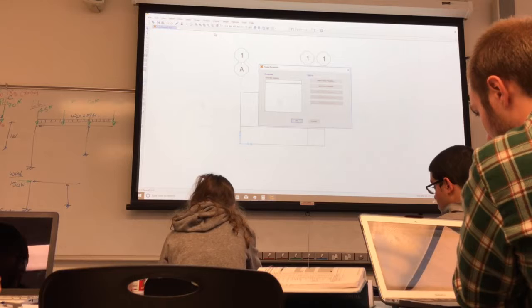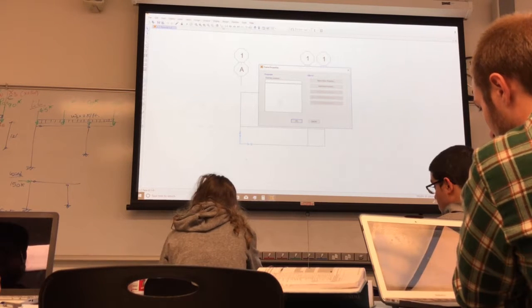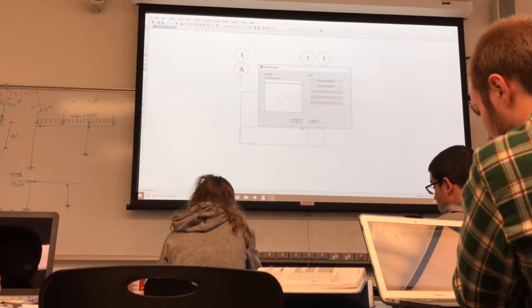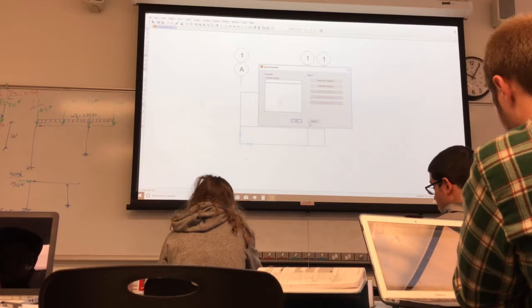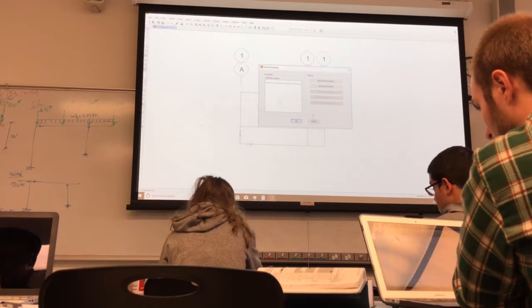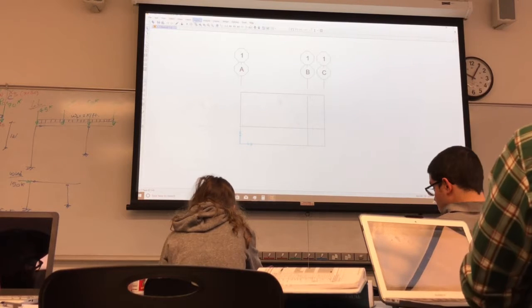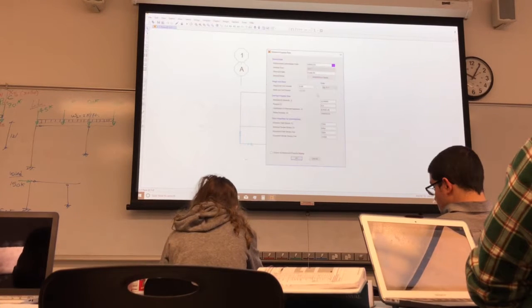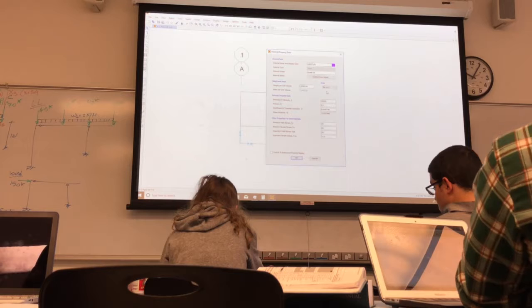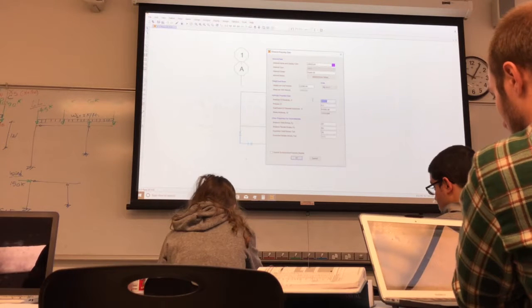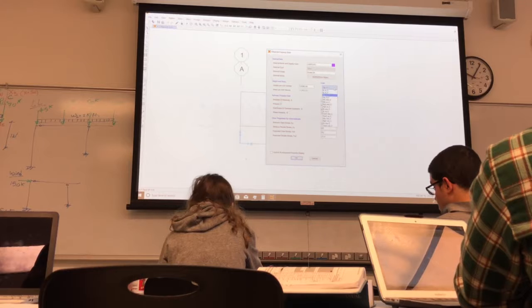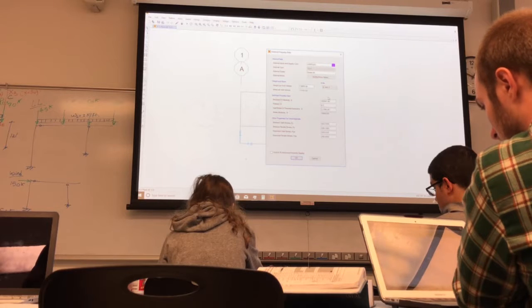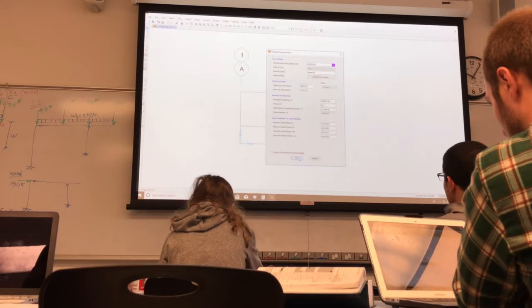Did you switch it back to KSI real quick, or you kept it PSI? For what? Well, you check to see if all the moduli will be different because you went to PSI, right? KSI. Yeah, 29,000 KSI. Did you keep it like that? Yeah, what I did is that I went to material and changed the units here to KSI, and then 29,000 KSI, right? If you want, we can do it in Newton millimeters, but I don't want to. It doesn't matter, it does the conversion for you, so you don't have to worry about any of that.